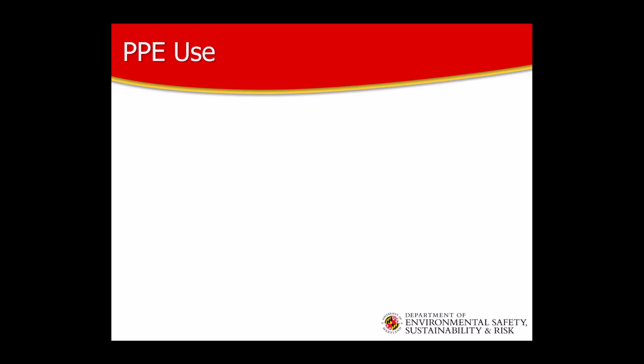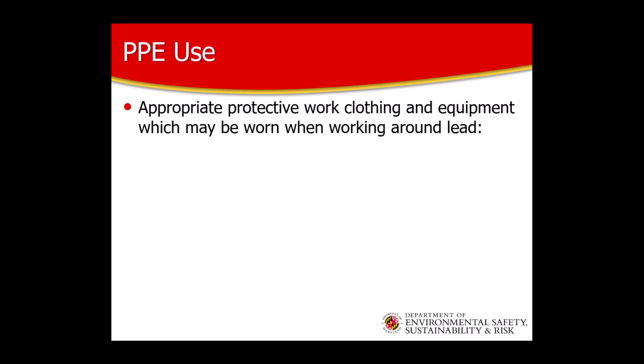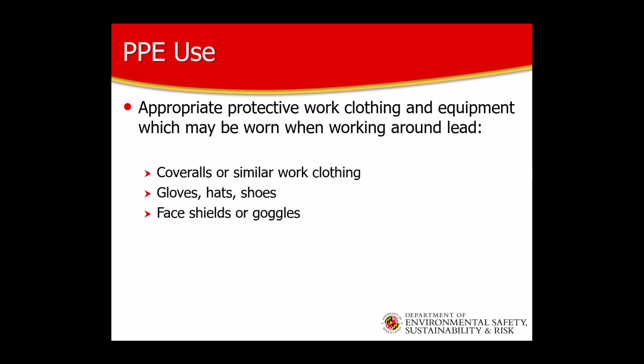PPE use is only required if an employee is exposed to lead above the PEL, but is still always a good work practice when coming into contact with any levels of lead. Coveralls or similar work clothing, gloves, hats, shoes, face shields, and/or safety glasses or goggles can be worn to protect against exposure.